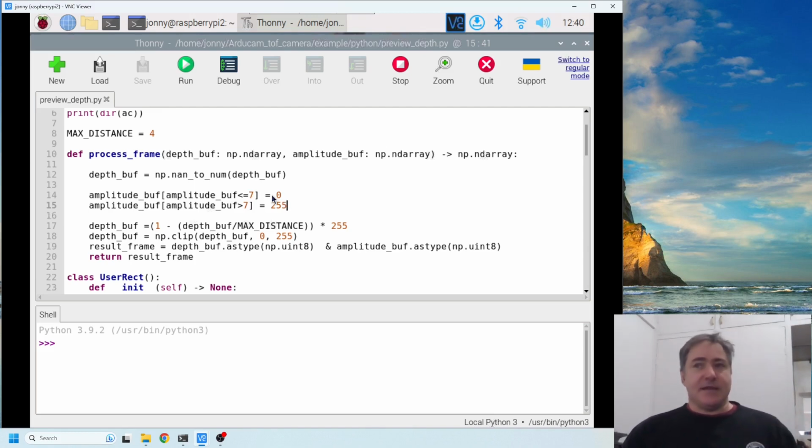So something that's 5 meters away, the camera is going to think that's actually just 1 meter away because it's traveled 8 meters when we fire off the next pulse. So 5 meters there, 3 meters back, so it's now 2 meters away. So we fire off this pulse, it travels 2 meters, and whatever it's traveled gets divided in half because it has to travel there and back.